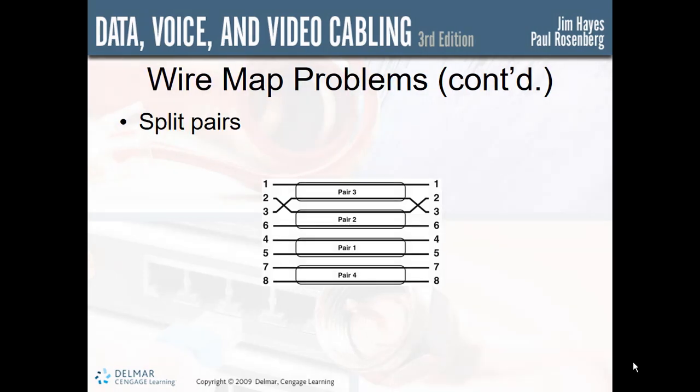A split pair, and we use a wiring verifier, will provide basic connection information, but some faults, like split pairs, may not show up in a wire map. A split pair occurs when one wire on each of 2 pairs is crossed at both ends.